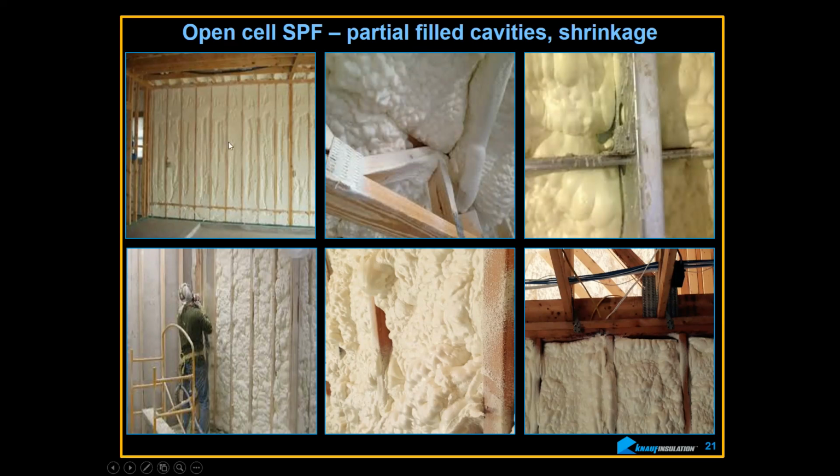It's more porous and more flexible than closed cell foam. It does have that advantage. The only problem with it is you're paying a lot of money just to get air sealing, because the R value of this stuff is around 3.3 to 3.4 per inch. You can get a fiberglass batt at 4.4 per inch, just as an example, and air seal as you would for a lot less money.